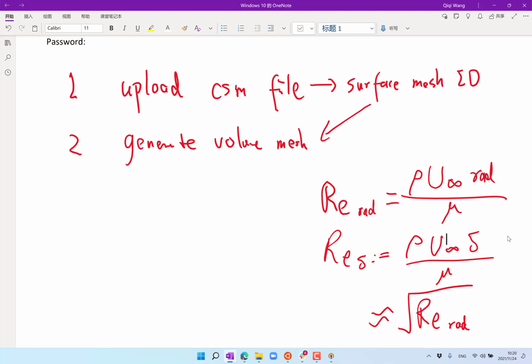On the other hand, if you make it thinner, the volume of fluid affected by the viscous forces also decreases proportionally. As a result, the thickness of the laminar boundary layer has a square effect. So essentially that's where the square root comes from. Okay.